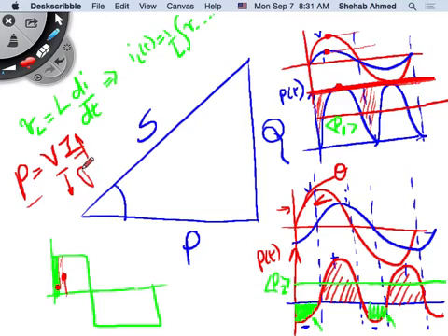What are losses in a cable equal to? Resistive losses. The cable is, for example, a resistor, right? I squared R. So if I want to transfer huge amounts of power using a DC system, I cannot live with a low voltage that is safe for people to use, right? I would have to step up the voltage to very high values.